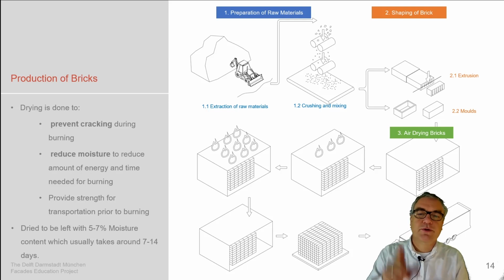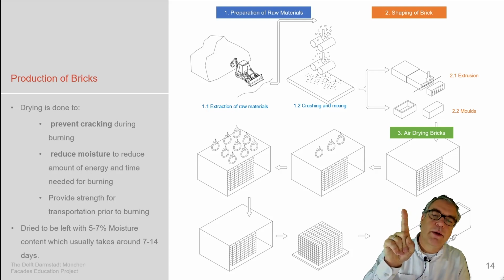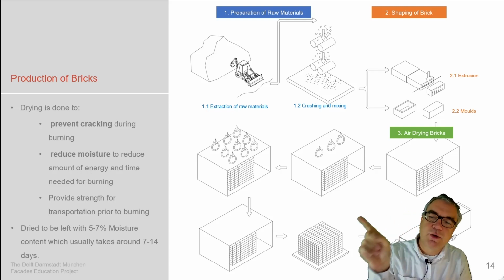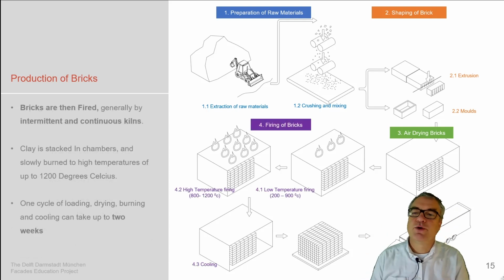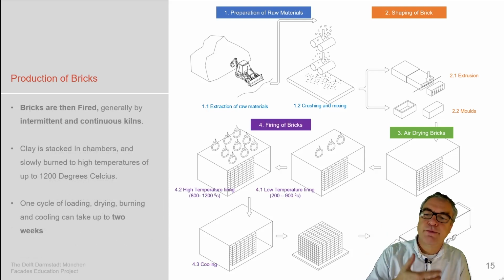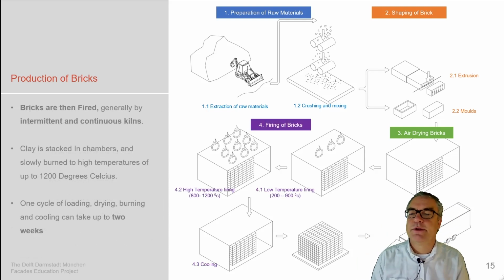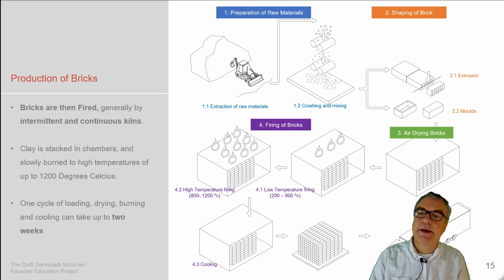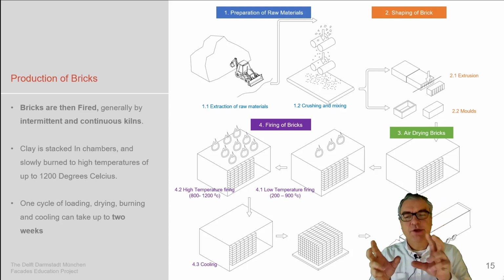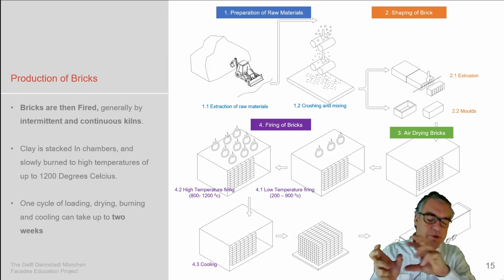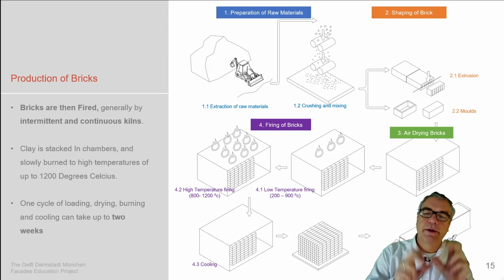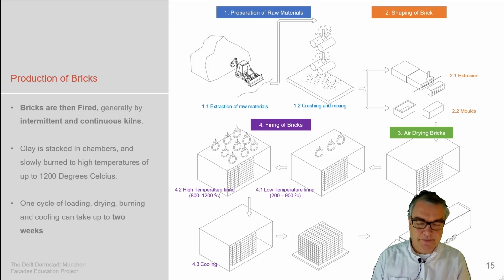Then this whole thing goes into a drying process. That's a quite long lasting process, and then into a firing process that is brought to certain temperatures, either low temperature in the first step and then higher temperature in the second step, to change the clay into the brick material, to crystallize the clay into a brick material as it is wanted.